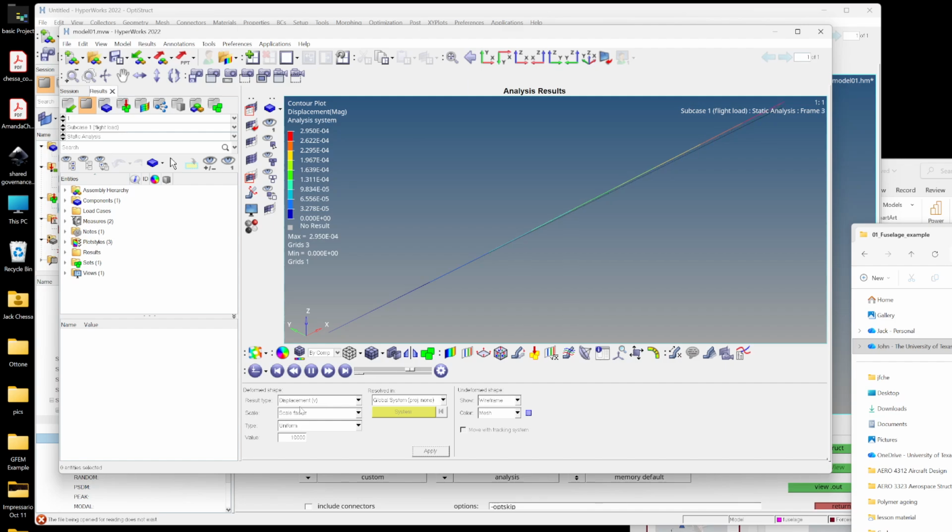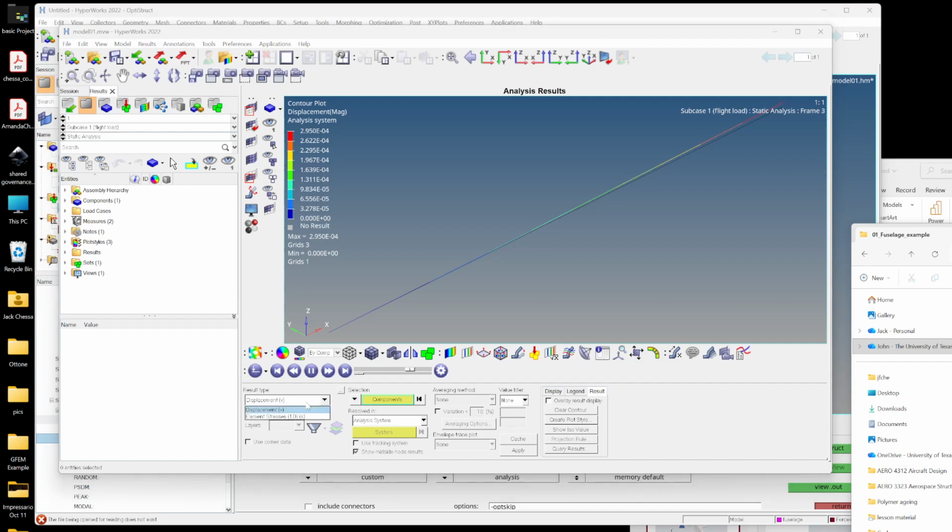Normally when we do flight loads, you would really do an inertial relief analysis, which we will talk about. But to get started, we're just making CBAR elements for now. So there you go. We can also shade it so we can see the stresses. So we can pick element stresses, and I should talk more about this.